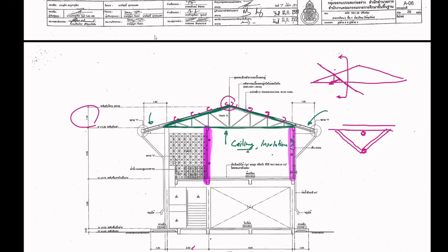Okay, how do you handle the weight of the truss? It's a uniform load, right? If you put the weight of the truss in your analysis, how would you do it? A hand calculation becomes impossible, right? Yes, because now we're talking about a frame with uniform load and axial load and everything.